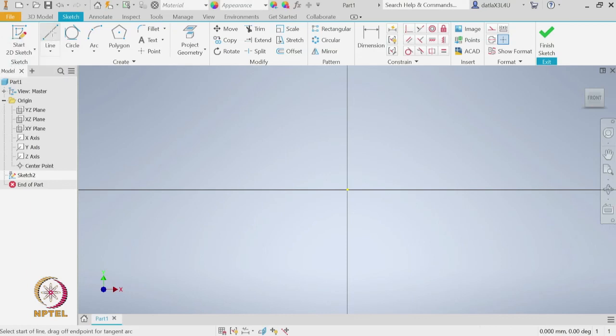So, I can start with a straight line, saying this is one straight line, 2, 3 and 4 points. I will select the escape button to say I am done with creating these multi segmented lines. Now let us use this extend button. Once I click this extend and come to this third line, it suggests that it will extend it until it reaches the first line segment. So, let us select it. This is how we extend a line until it reaches another entity. In this case it is the first line segment.